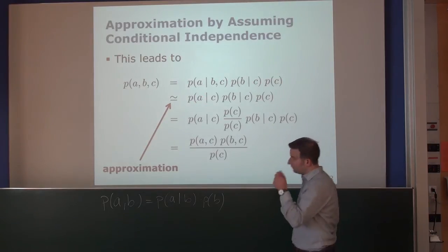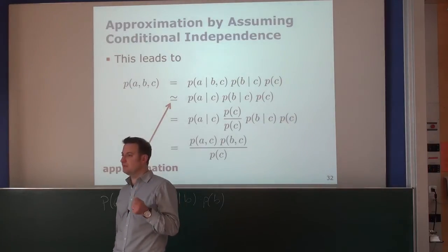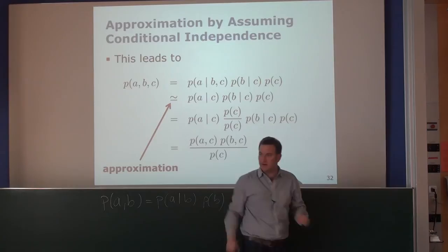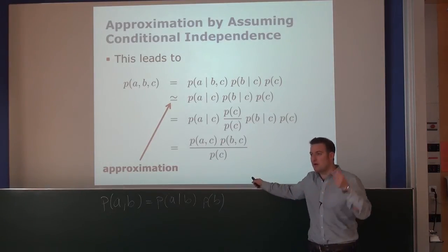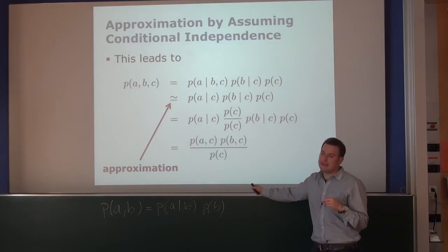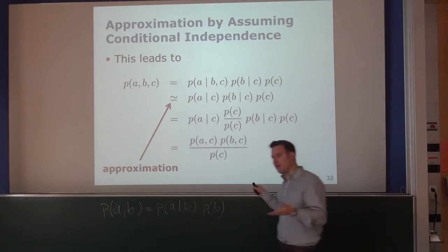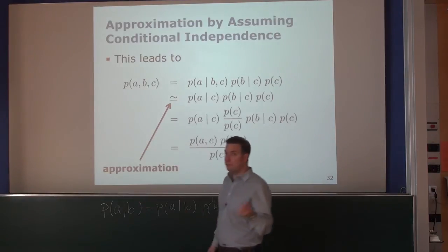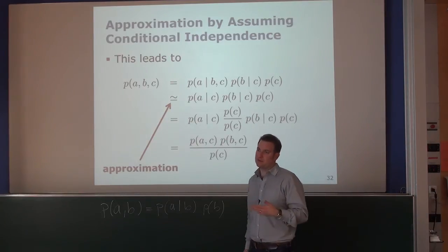And this is, I assume that A and B are independent of each other given C. This exactly corresponds to getting rid of those, or having 0 off-diagonal elements between A and B here. So A could be the robot's pose at time t+1 in the previous example. B would be the landmark M1, and C would be all the other dimensions, in this case landmark M2.